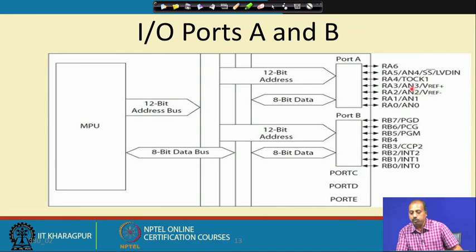These are also used so you can connect some ADC through this, and whenever you are doing analog to digital conversion, then these analog channels can be connected there. So, there are 4 analog channels that can be connected for analog to digital conversion, and VREF plus and VREF minus are used for the ADC. Then there are some other pins, like one for timer clock, and some other control bits. You can find out their meaning from the manual.